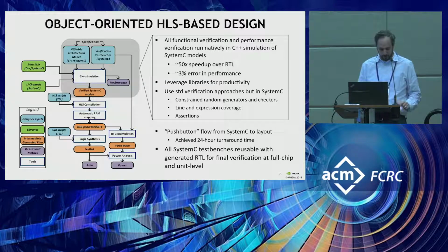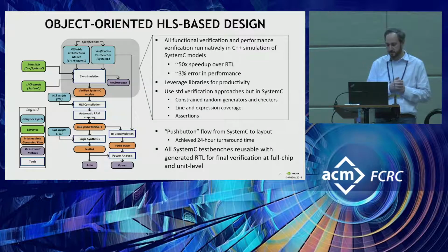Libraries improve productivity, and we essentially use standard verification approaches, like everything we use in digital design: constrained random generators, checkers, line expression coverage, functional coverage, assertions, et cetera. We do all that stuff basically the same. We're just doing it all at the C++ level instead of the RTL level.